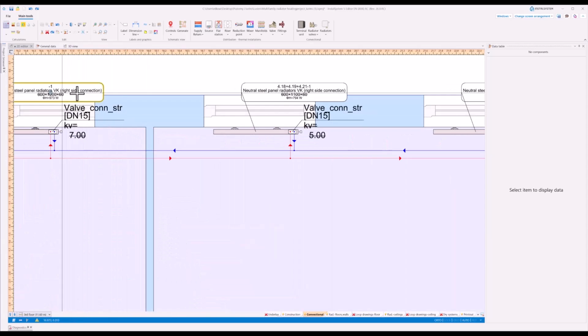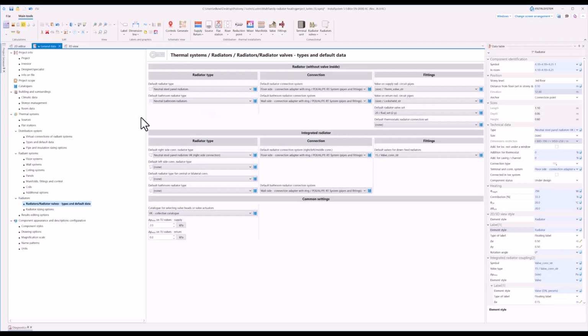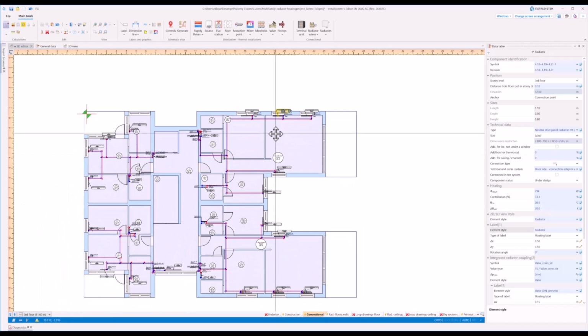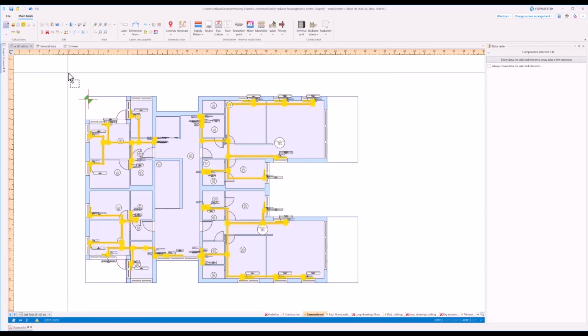All mentioned functions also allow for similarly copying installation elements. It is possible to rotate and mirror copy radiators, receivers, distribution network, or radiant installations along with the pipe feed routes. The program ensures the correct direction of the reflection of installation elements, for example, radiators.